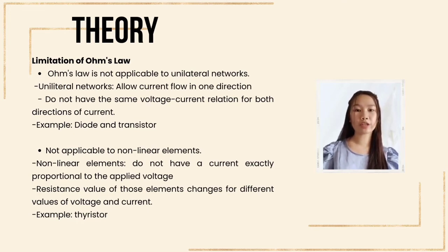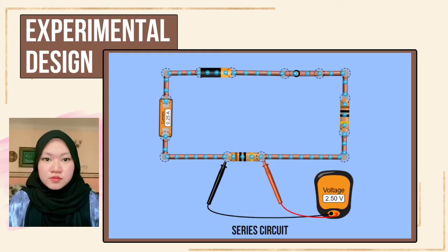Secondly, it is not applicable to nonlinear elements. Nonlinear elements are those which do not have current exactly proportional to the applied voltage, which means the resistance value of these elements changes for different values of voltage and current. An example of a nonlinear element is the thyristor.